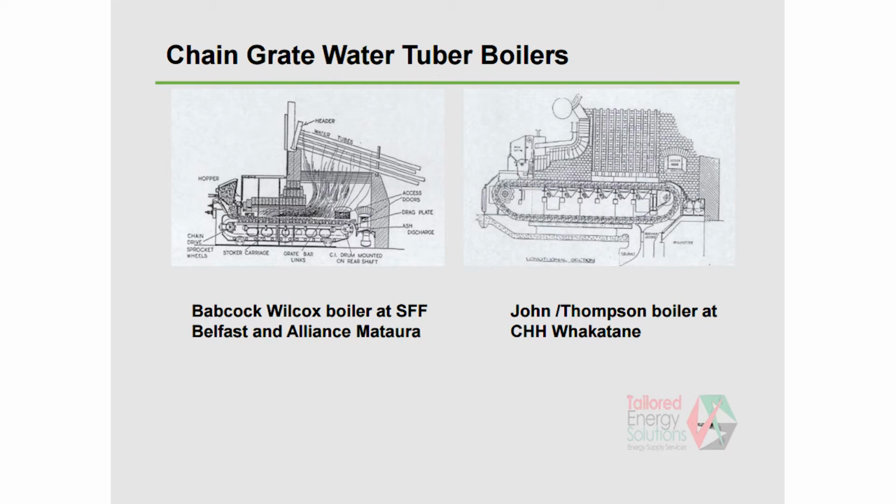So they opened the arch up and put the hog fuel into that boiler to carry on, because the hog fuel is so wet, not easy to get ignited. So they use the coal to start the fire and provide the heat, so the wet wood is dropped on the hot bed. That's the only way to burn. Another chamber boiler anyway.